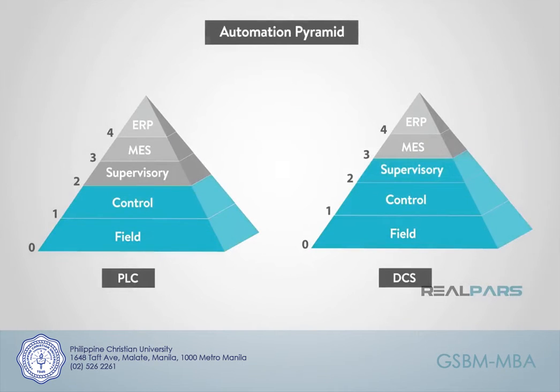DCSs also have a claim that when safety is a top priority, the DCS is the most reliable system. The reason for this is because the manufacturer supplies both the control and supervisory equipment as an integrated package. The risks of integration errors are greatly reduced.